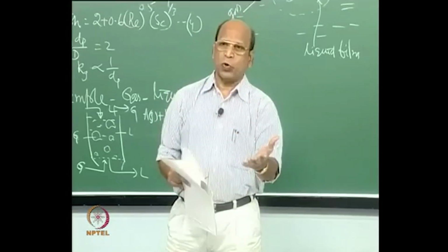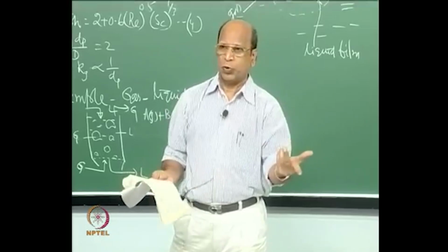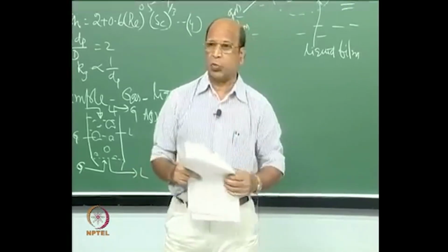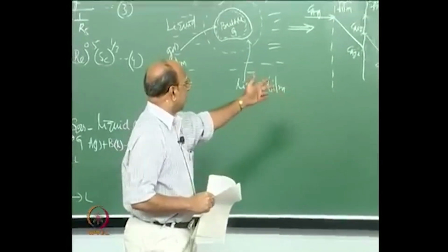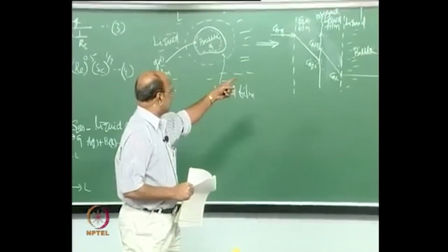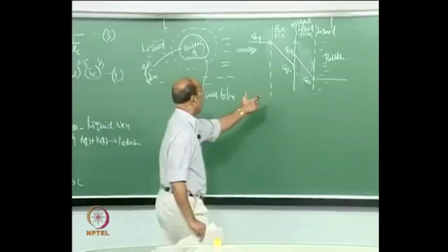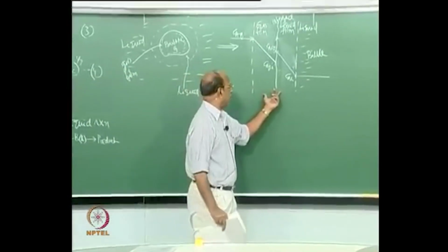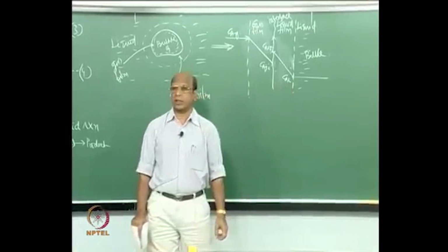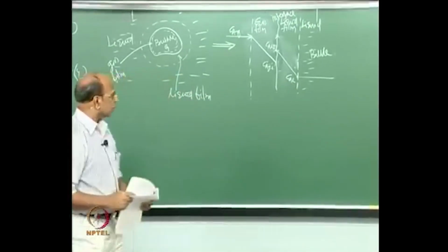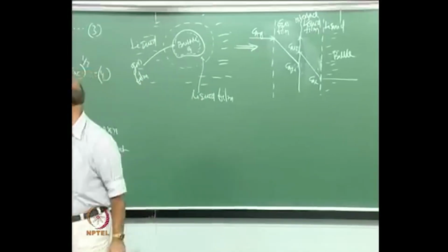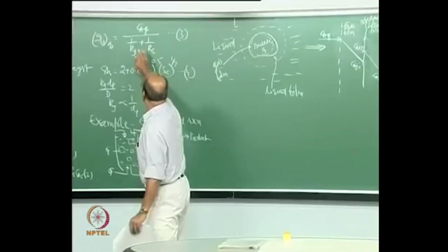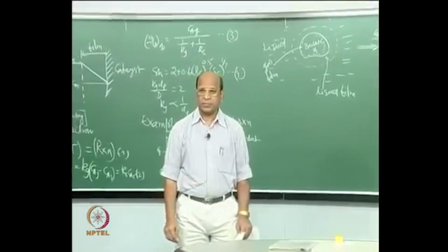But if I have only pure gas, and most of the time we use pure gas, for example, hydrogenation of vegetable oils, which is also a very good example for that, then with assumptions like pure gas, this will disappear totally. Then I will have only the liquid film coming into the picture. So with these assumptions one can now write the actual equations, like we developed the observed rate.